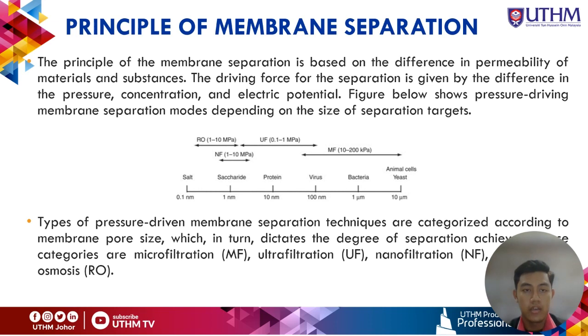I will continue the presentation and I will talk about the principle of membrane separation. The principle of membrane separation is based on the difference in permeability of materials and substances. The driving force for the separation is given by the difference in pressure, concentration, and electric potential. And the figure below shows the pressure driven membrane separation modes depending on the size of the separation target.